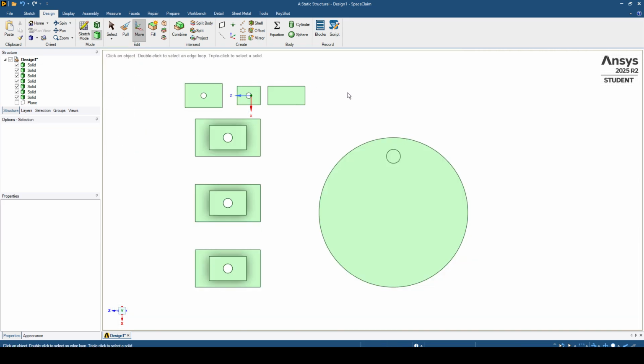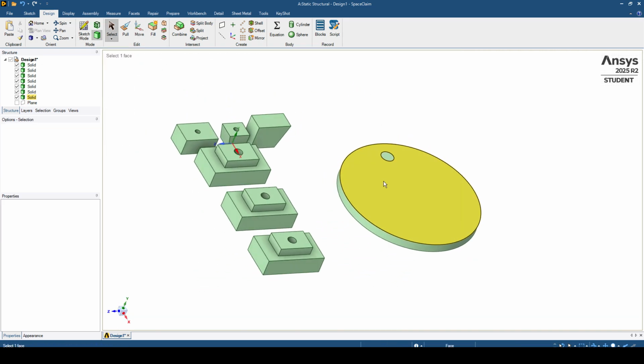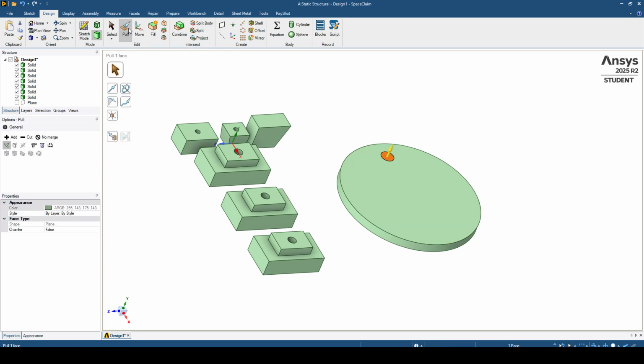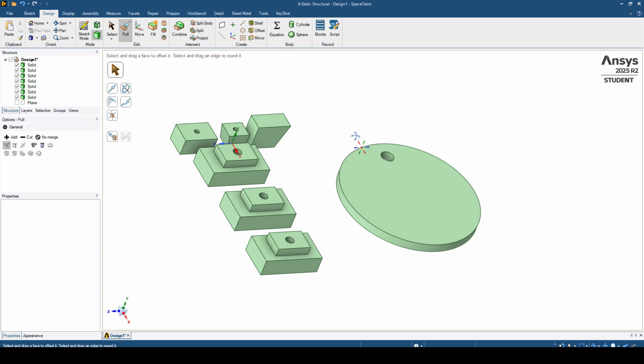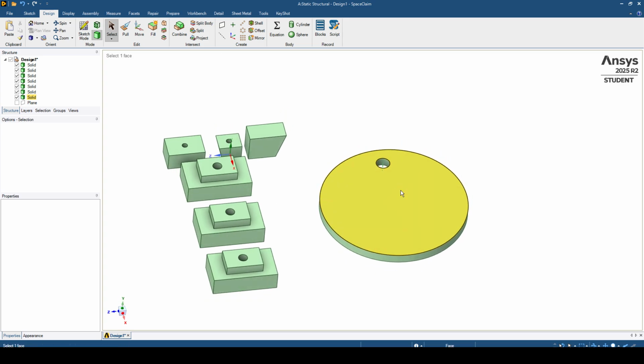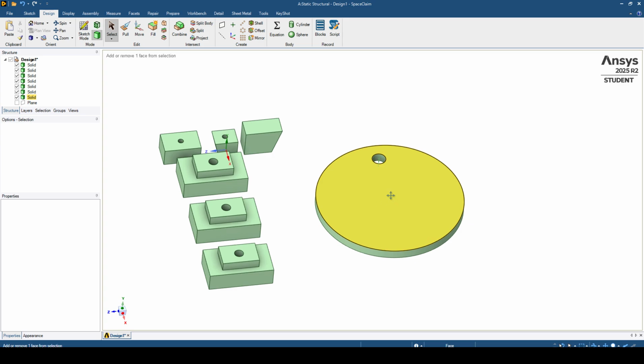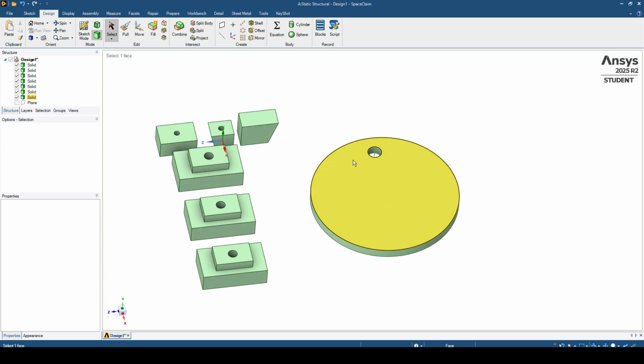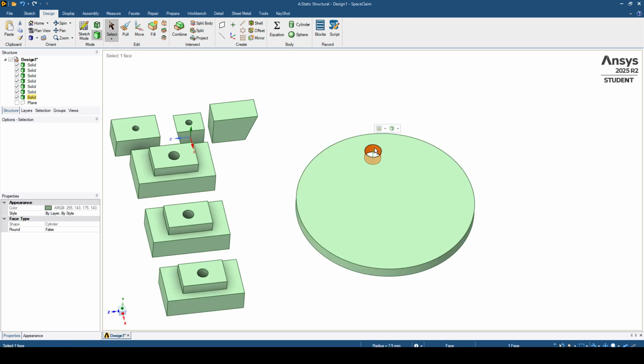Now let's cut this circular form to create a hole. I go to pull and create cut, and from the working design I will drag downward, and as you can see now we have this hole which is 60 millimeter away from the center. Now in order to use the pattern as an example in our episode right now, I will go and click on this hole.